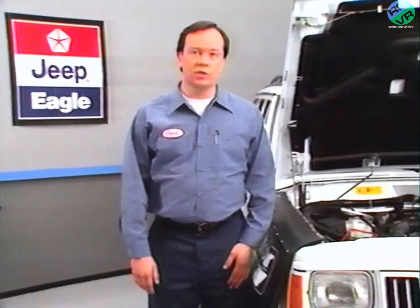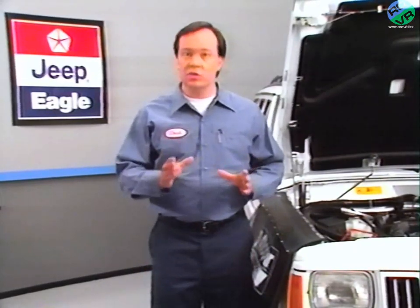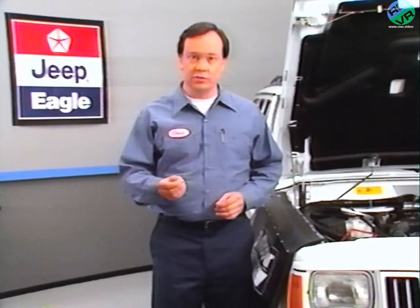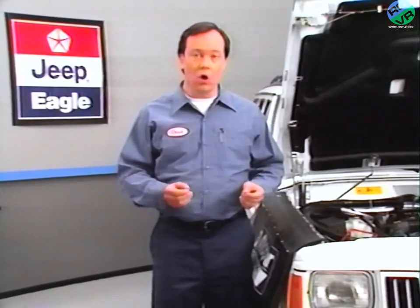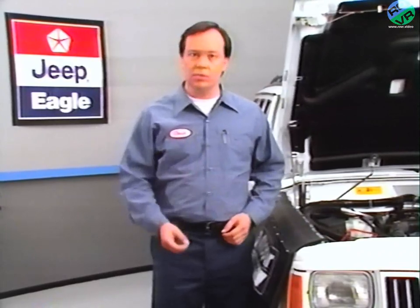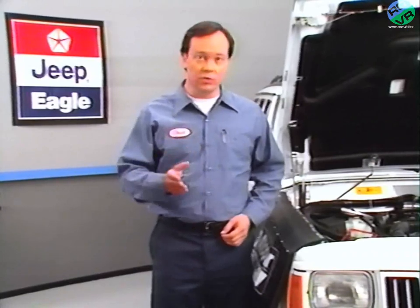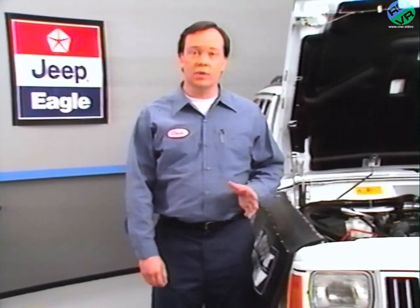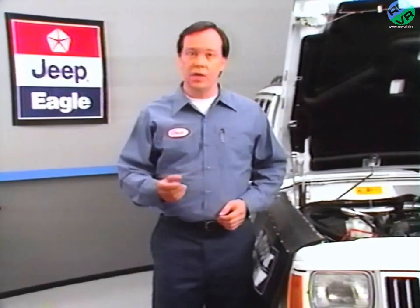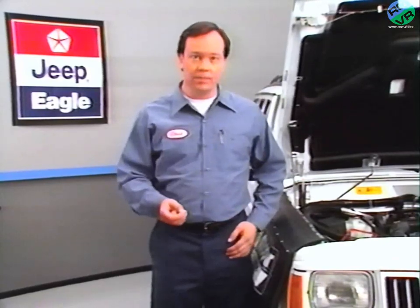It's important to remember that what we're dealing with is a fuel injection system, a system that's made up of various input sensors and output actuators, all of which are controlled by the engine controller. If there's a problem with the fuel injection system, don't just assume that the engine controller is faulty and needs to be replaced. The cause of poor drivability or a no-start condition may be a bad connection or a faulty sensor or actuator, and not a bad engine controller.